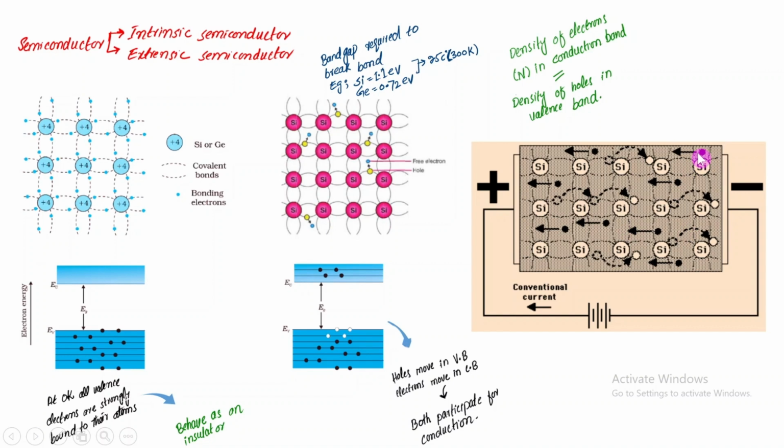On the other hand, if the electron moves in this way and fills this hole, the hole will be present behind it. In other words, we have this positive charge and this negative charge, and a hole is actually a quasi-static particle with positive charge. Holes will be repelled from this side and attracted toward this negative cathode.